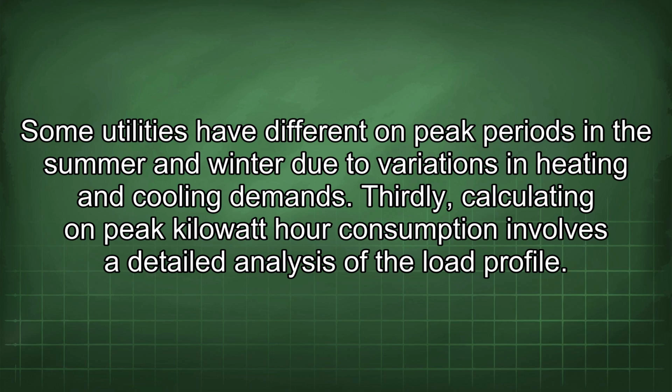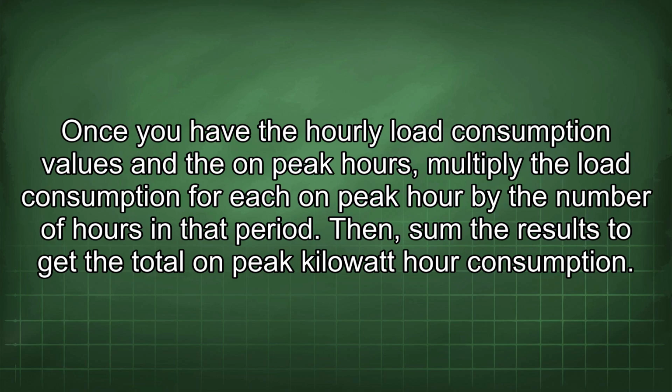Thirdly, calculating on-peak kilowatt-hour consumption involves a detailed analysis of the load profile. Once you have the hourly load consumption values and the on-peak hours, multiply the load consumption for each on-peak hour by the number of hours in that period. Then sum the results to get the total on-peak kilowatt-hour consumption.